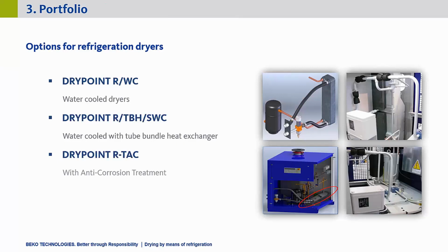And then again, the last one is the oil-free version, of course. Oil-free just means that you do not contaminate your compressed air system downstream of the treatment. So if you have, for example, an activated carbon tower installed or a catalytic converter or whatever you have, everything behind this treatment needs to be oil-free. And this is what this dryer has, so you do not contaminate your system. Yeah, and these are actually the main options that we have.